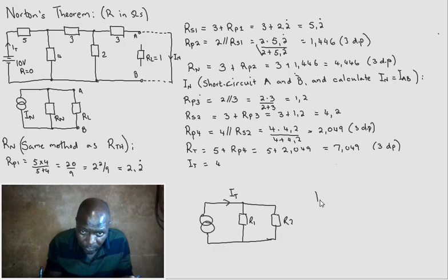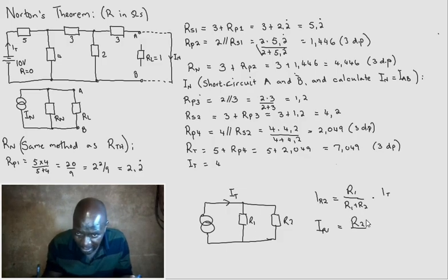So I R2 is equal to R1 over R1 plus R2, times the incoming current I total. When I want the current through R1, I use the other resistance here. It's rather a ratio of rejection. The current rejected by that comes here, and the current rejected by that goes there.